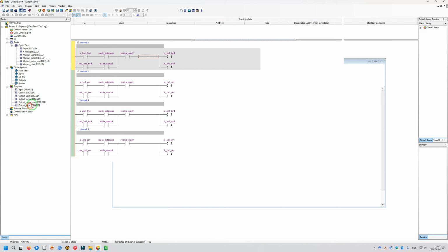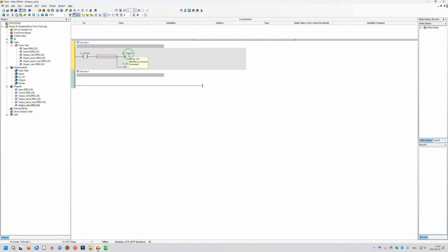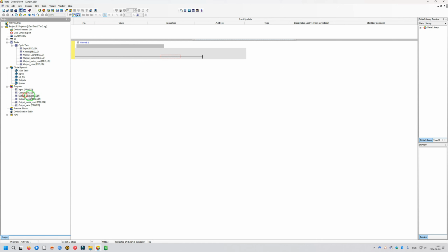so we can run this motor only in this way, but I will delete this one. But for example, for the vacuum, let's imagine we grip something and lift, and we don't want to lose this signal by pressing emergency stop button or something, because it's the vacuum suction pads, so we will lose the product. So what I'm going to do, I am going to use only this one bit in this subroutine, and let's go to our LED.